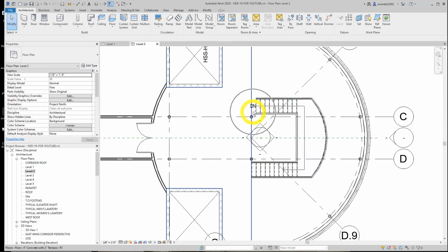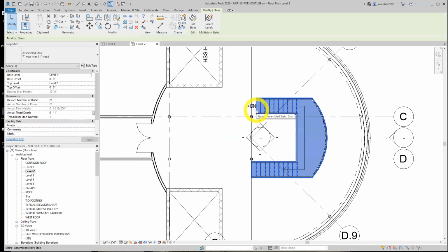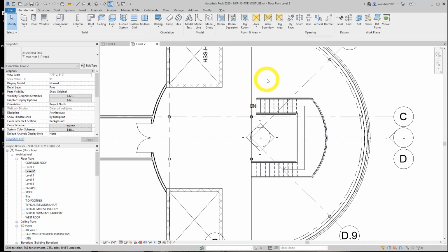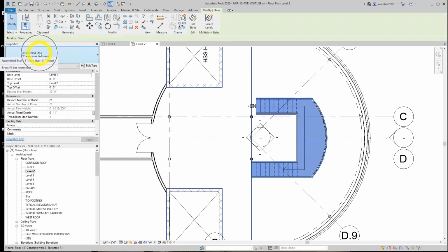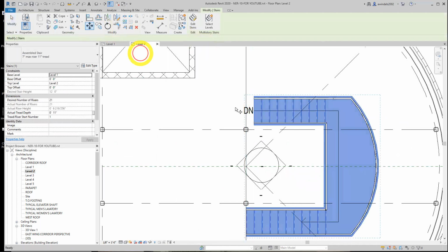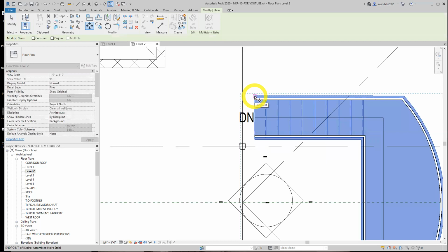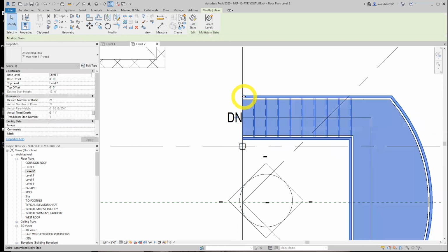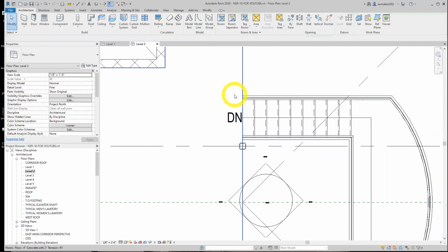We don't want this gap. It's basically saying we're going to move the entire stairs. Basically, they did that intentionally to say we put them in the wrong spot. So I'm just going to select the stairs. You can tell you selected them somewhere on the face here, and make sure you have them selected. Always check your properties, check down here, see what you have selected. It's easy to not select the stairs, and let's hit move. Let's pick an endpoint here, and let's just move them to the face of the floor edge right here. On the second pick, escape. That's it on that.